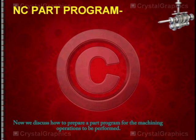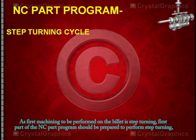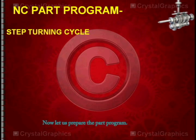Now let us prepare an NC part program for performing the machining operation shown in the workpiece layout before. As the first machining to be performed on the billet is step turning, the first part of the NC program should be prepared to perform step turning to produce a step of dia 20 mm up to 35 mm length. Now let us prepare the part program.